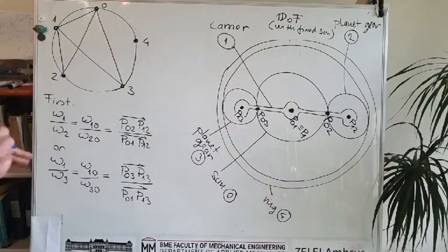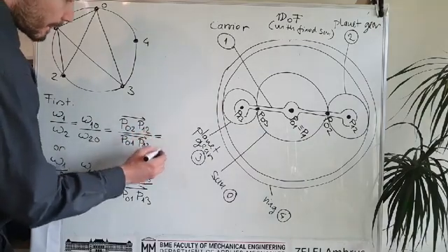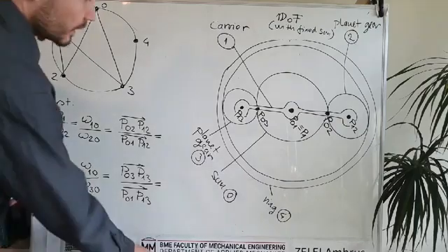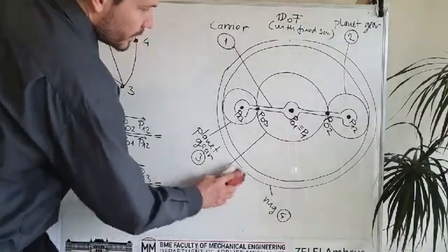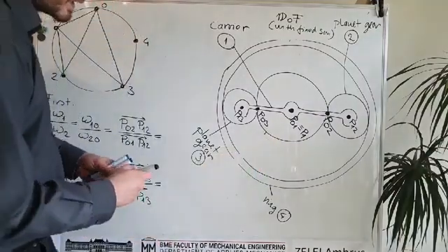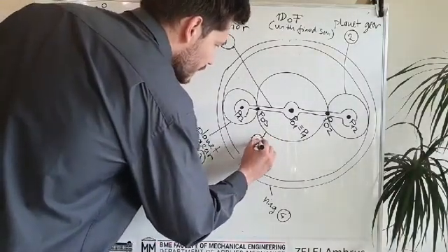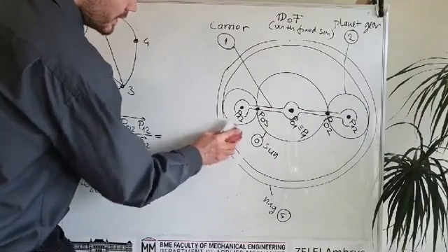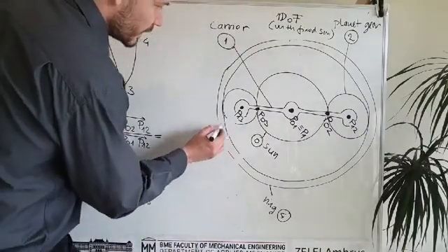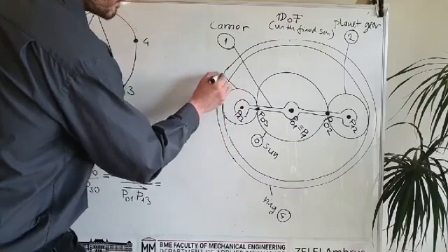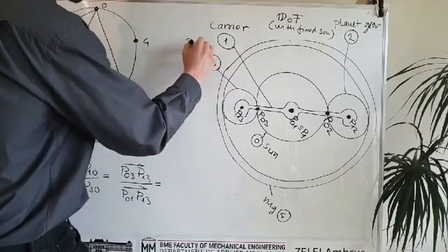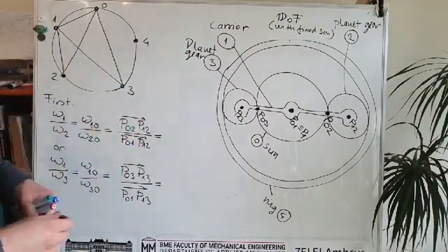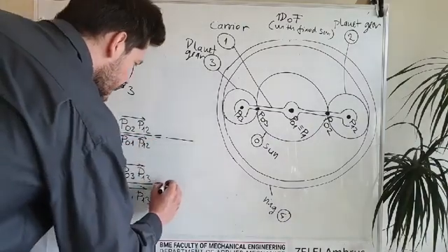and we could draw a lot of Kennedy lines, but if it's not necessary we don't do it, and it is not necessary so far because we have all of these points and we are able to calculate the formula. Okay, so this is the rigid body number 0, which is the Sun. I have to save some space. Planet gear 3 is here. So I think we have everything we need here, and let's try to evaluate the formula.